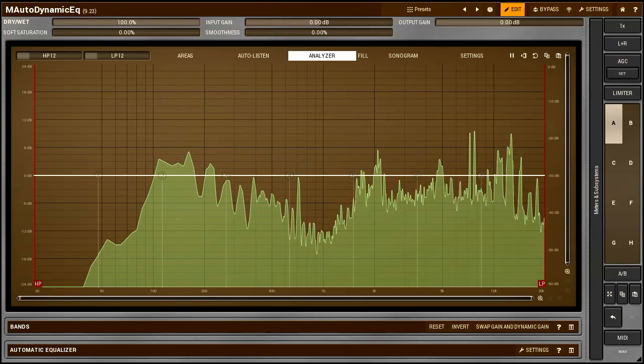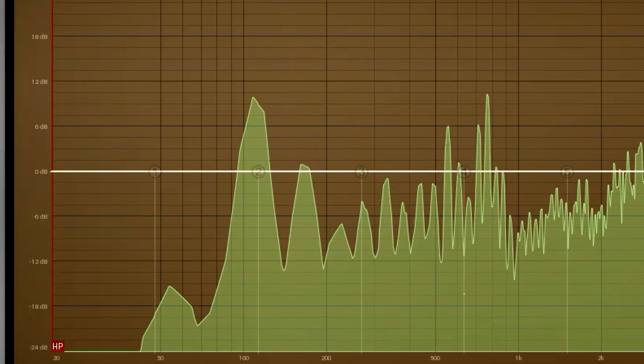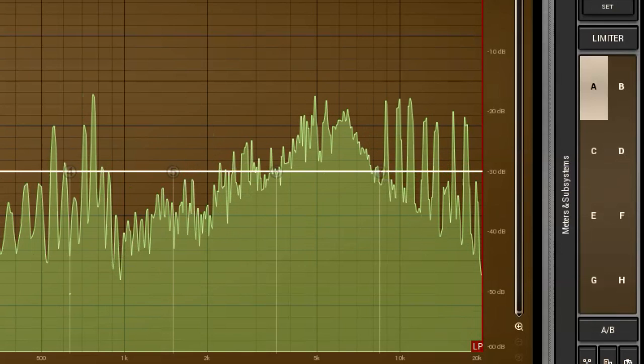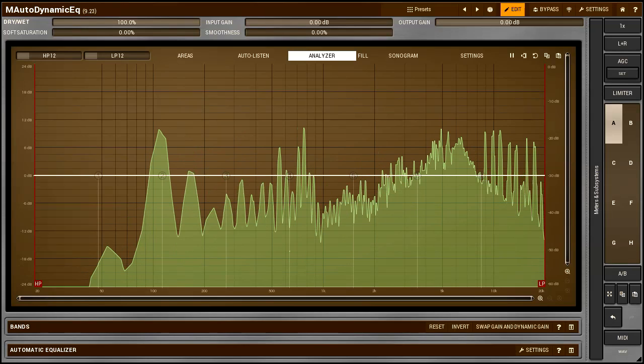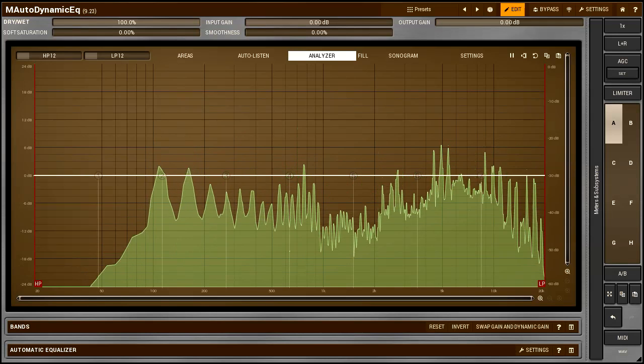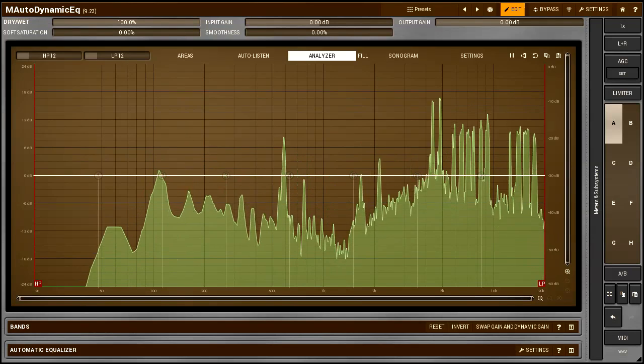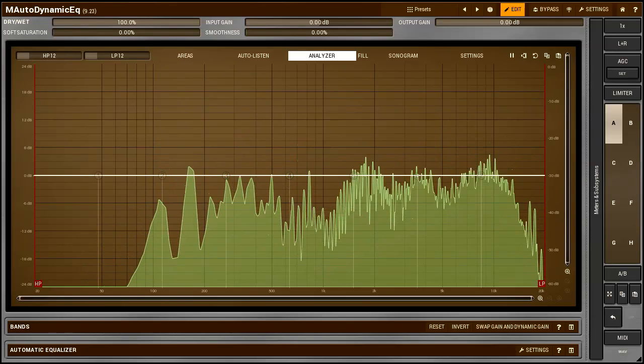You may ask, why do the peaks on the left side look thicker than those on the right one? You see, the FFT algorithm wasn't originally created for audio signal analysis, and this is the result of the FFT algorithm's adaptation to the way we perceive a signal's pitch. Our brain analyzes pitch in logarithmic scale that you can see on the bottom axis. However, the FFT algorithm works in so-called linear scale. The analyzer needs to transform one into another, and this is the payoff. As a consequence, the FFT analyzers have worse resolution in low frequencies than in high ones.